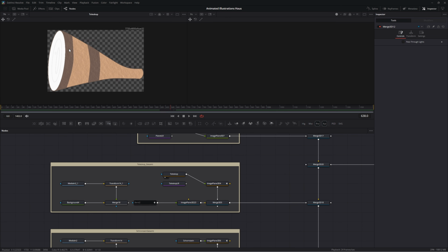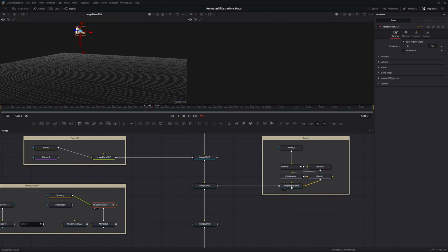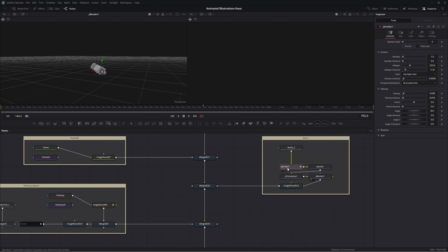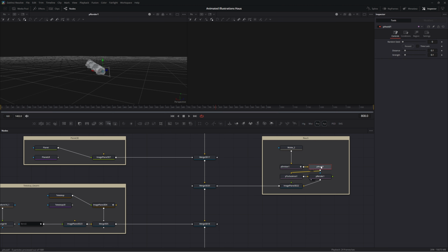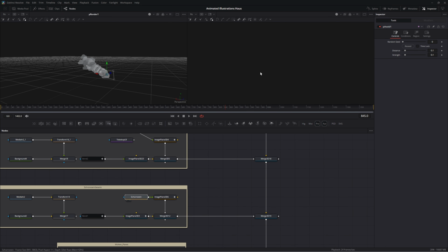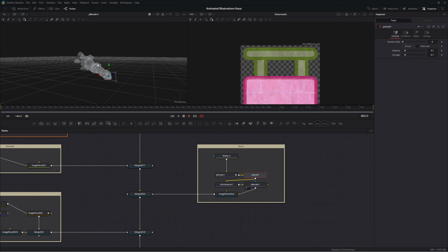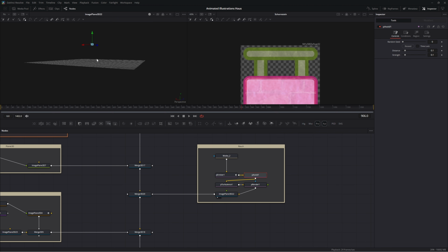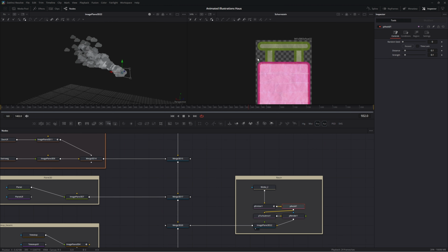It's really similar for the telescope. It's just an image put into 3D, and then there's also an animation going on. The chimney has a twig up its sleeve. These clouds are fed into a particle emitter with the style set to bitmap. Then I added a pAvoid to make them follow the chimney texture right here, so that they hit this green thing. And to give it a bit more variance, I added a pTurbulence, and then it's rendered and put into an image plane at the same position of this chimney. Then it looks like smoke is coming out of a chimney.